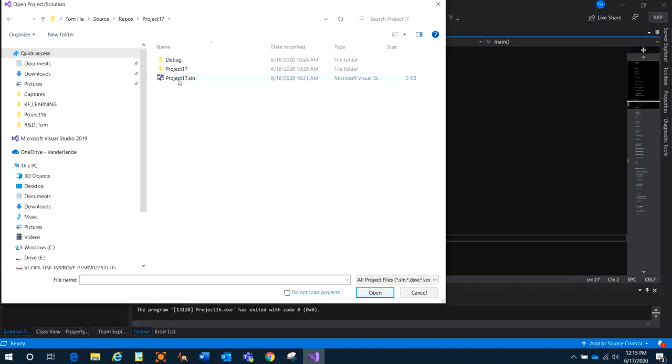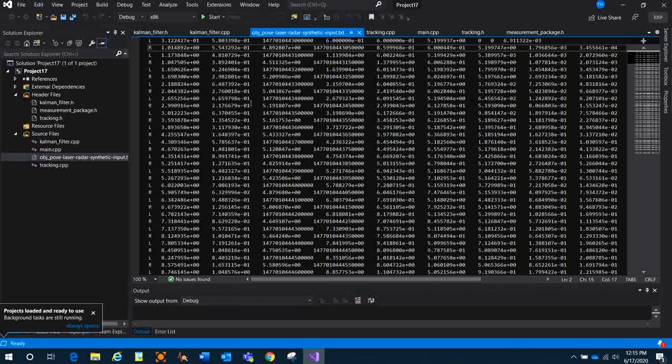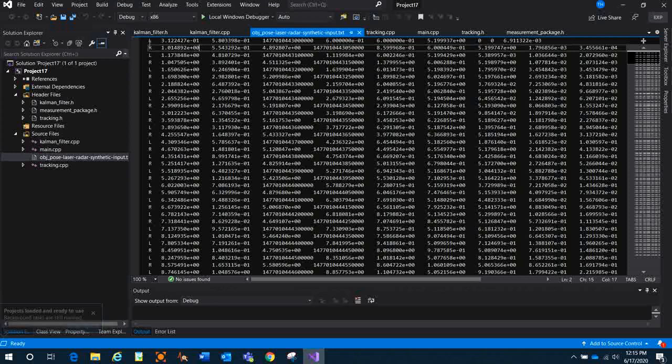We talked about tracking a pedestrian with four dimensions: the position and the velocity. Here is the TXT file. This file shows you the values we got from the fusion sensor. We have to capture the value, whether it is laser or radar. For laser you have position x, position y and timestamp. We need the time between two measurements for the laser to calculate the delta t, right? And the radar data right here, I will tell you later what the values mean,